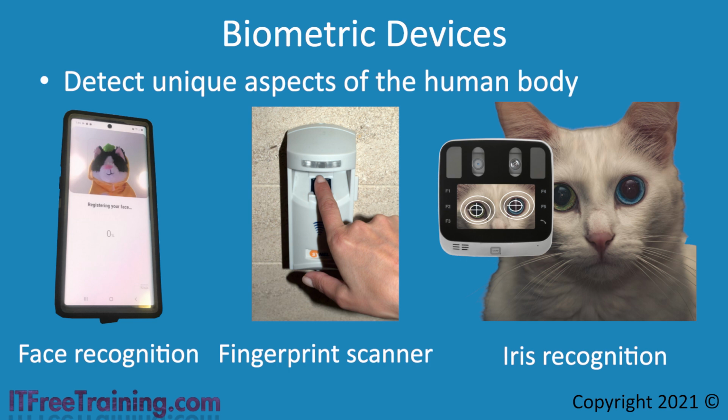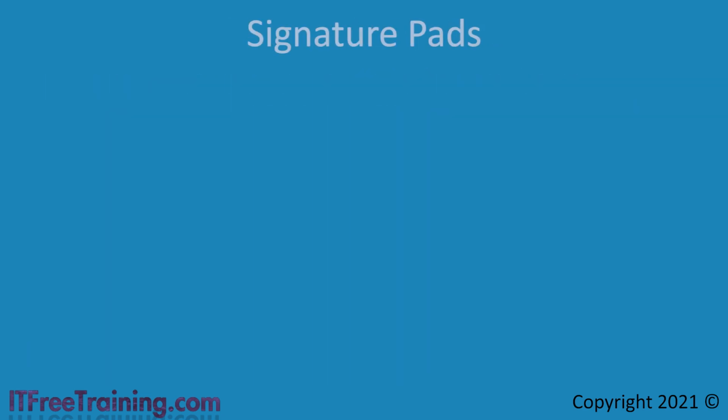Biometric devices are getting better, but can sometimes not authenticate correctly, even when the right person is using them. Depending on the type of sensor, too little or too much light can affect them. Injuries like cuts or wearing glasses can also affect them. Generally, if you are installing these devices, you would install them so they are in a well-lit area, but not in direct sunlight.